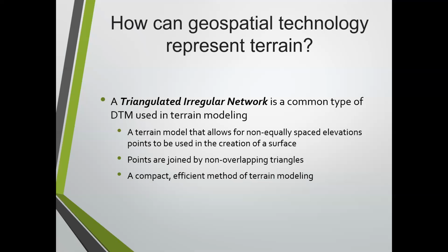You can go in there and just dump those points in. You've probably got a pretty good model with maybe 80%. But then you have to incorporate the break lines. All I was getting at is, yeah, you can go in and manually flip them all so they line up with your break lines. Yeah, absolutely. And of course, that's where you get into the editing. You can do what's called flip a face, or swap it. Sometimes it's called swapping. You can also add lines and delete triangles.